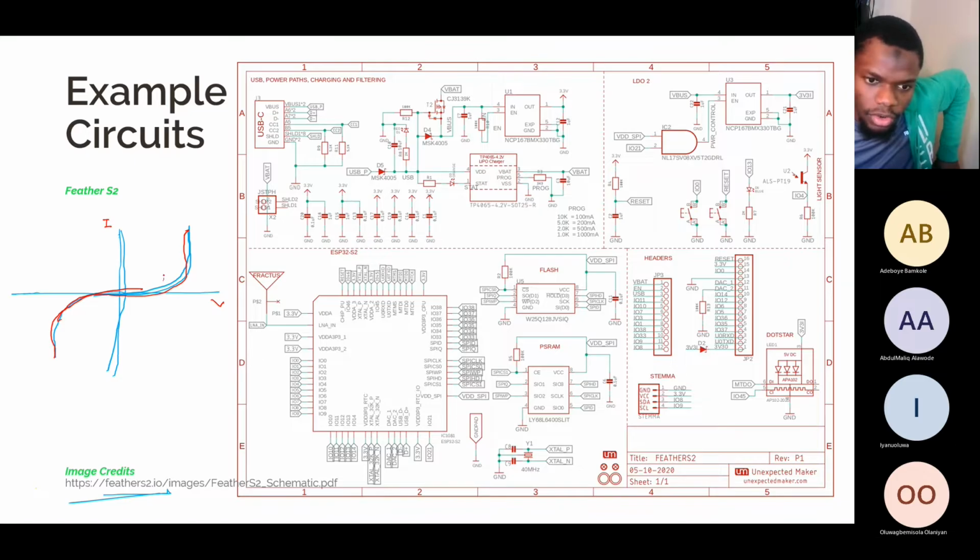So the current only starts flowing at a particular voltage if you forward bias it, and the current only starts flowing at a particular voltage if you reverse bias it. So current doesn't flow within this range. That's why you can have a Zener diode doing bidirectional usage, kind of. But usually they use it in the reverse bias mode because it helps to keep the voltage constant and things like that.